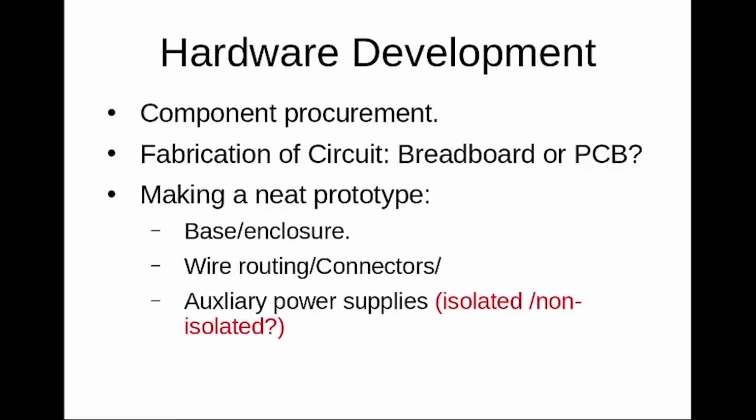If you cannot afford to buy extra power supplies, you may provide enough connectors on the board for receiving power from lab power supplies. But be aware of the isolation requirements of power supplies.